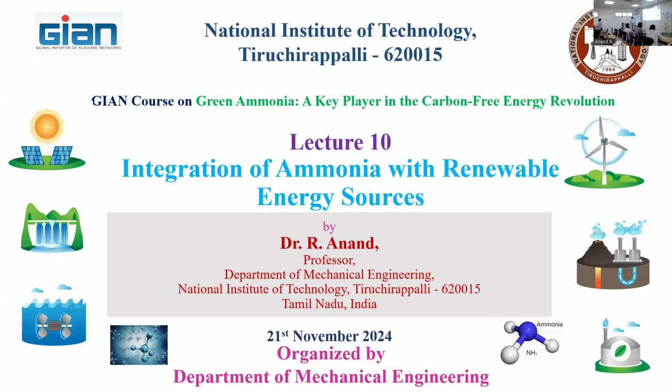Here, the organic Rankine cycle, ORC: in the organic Rankine cycle, the working fluid is not water. The working fluid is a low temperature fluid, preferably a refrigerant. So we can use ammonia, whatever the refrigerant may be, okay? Chlorofluorocarbons, freons, then hydrocarbon refrigerants. We have to ensure that the boiling point of the working fluid is such that, even at atmospheric temperature, it can produce vapor.